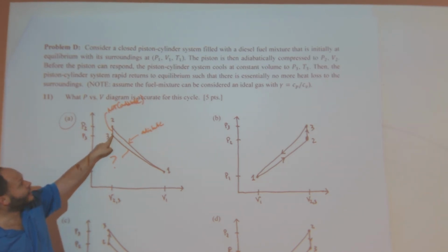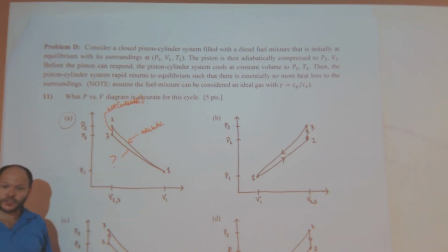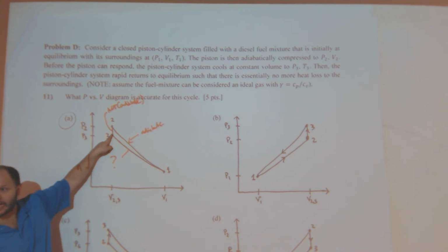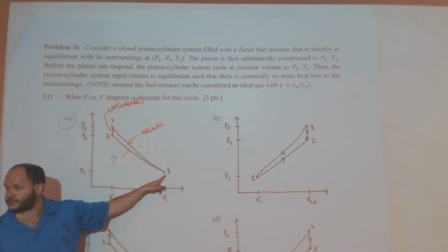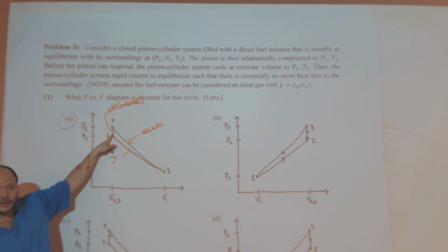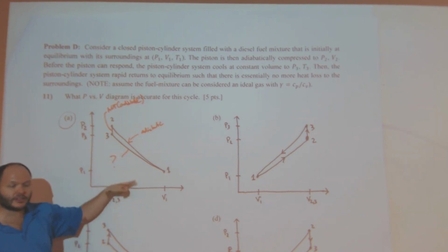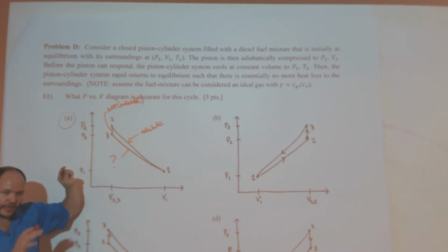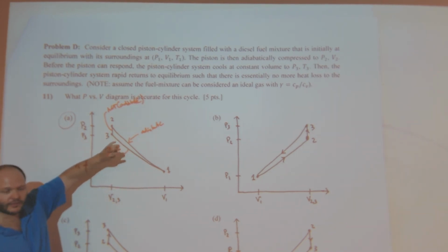But here, it's no longer adiabatic. As soon as I destroyed the adiabatic boundary conditions, I cannot take an adiabatic process back to equilibrium. I lost energy. There's no way to get back to here with less energy than I had before. This cannot be an adiabatic process. Okay, we'll get to that in a minute, but this is the right one,